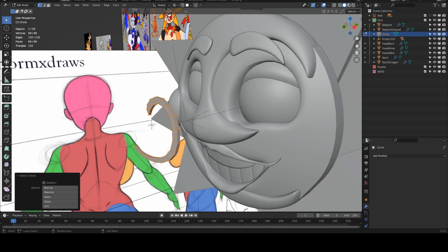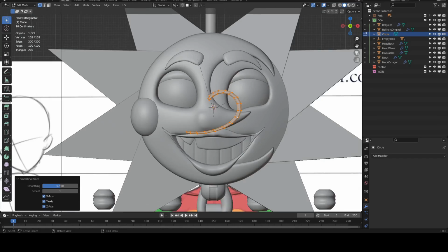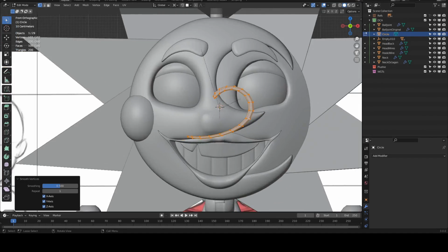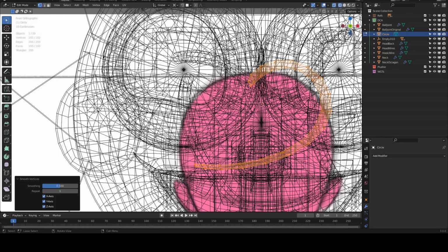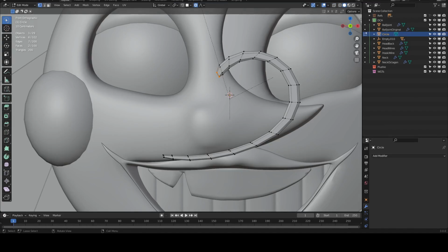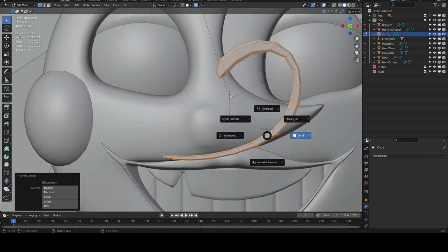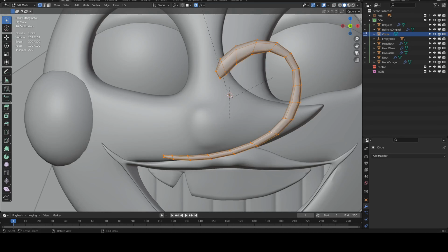And select all these, and actually, yeah, just put one curve right here. Select them all. Subdivide, not subdivide, smooth about 3 times. Select right here. Turn back on proportional editing again, and just make that one bigger. Whoops. Smooth.